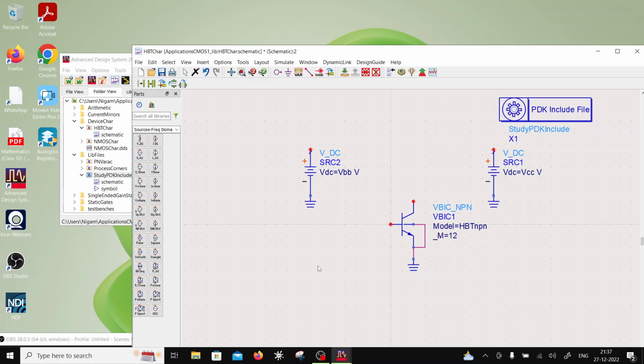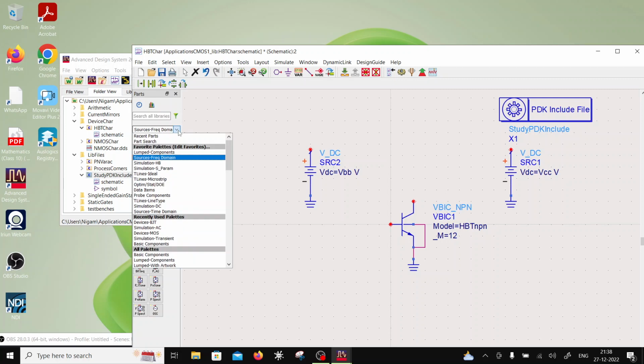Now these are the two regions in a Smith chart, short and open, which tend to be unstable. So rather we would terminate this transistor for RF at the center of the Smith chart, which is most likely to be stable, right? Because the DC characteristics will not mean anything if the device is oscillating, right? Okay, so for that we have to place the termination of the transistors to 50 ohm before I do a DC characteristics. Okay, so let's quickly do it.